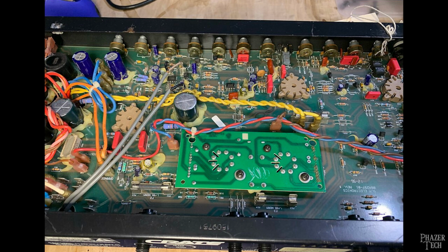For example, since an audio preamp signal is low power, power efficiency is not a concern with transistors in this case. And since relays require power to energize their coil, this is actually a scenario where power consumption will probably be lower by using transistors instead.